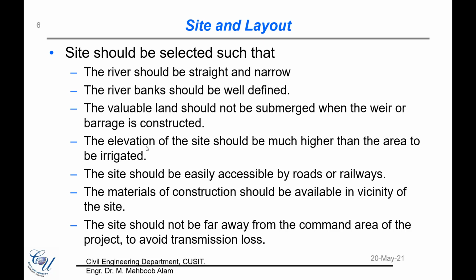If we look at the requirement of the site for diversion headwork or the layout of it, it should be kept in mind that the area should be so selected that the river at that particular section or at that particular site is straight and narrow. We need it straight because we need to divert water and we want most of the water to enter into the channel, and we want it to be narrow because we kind of